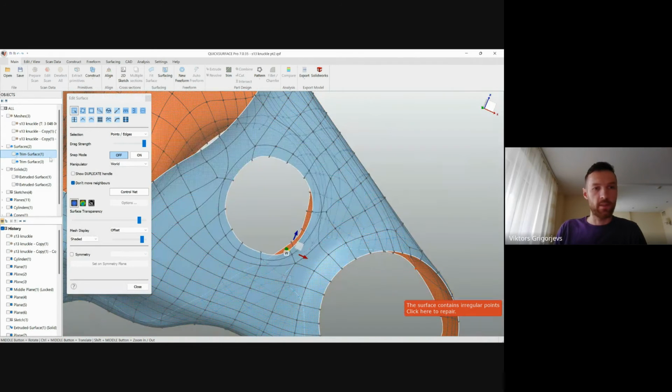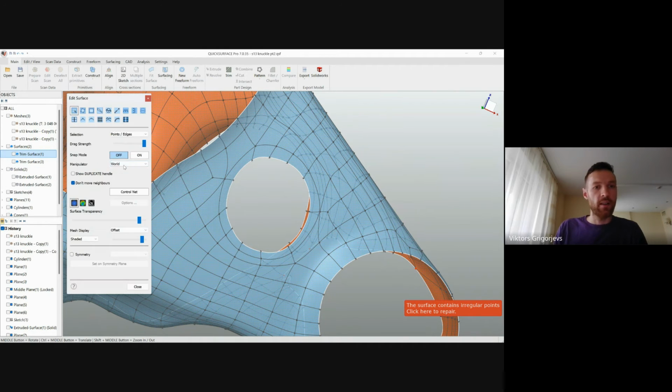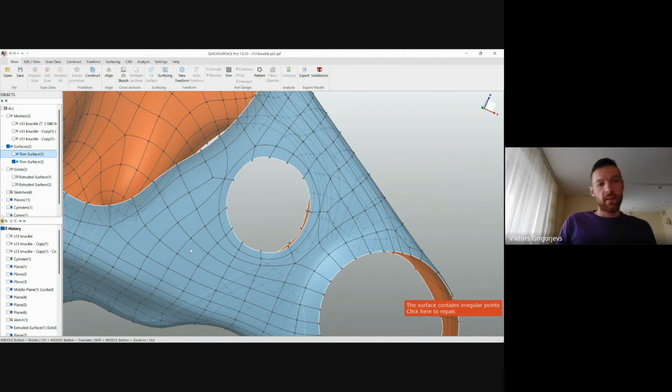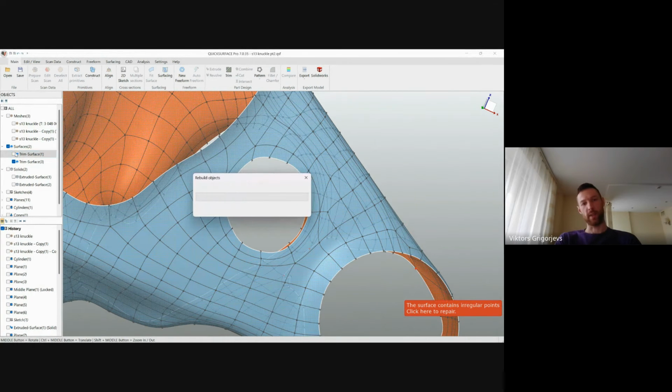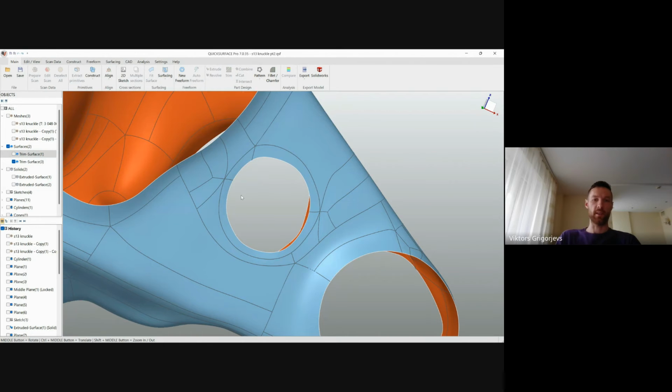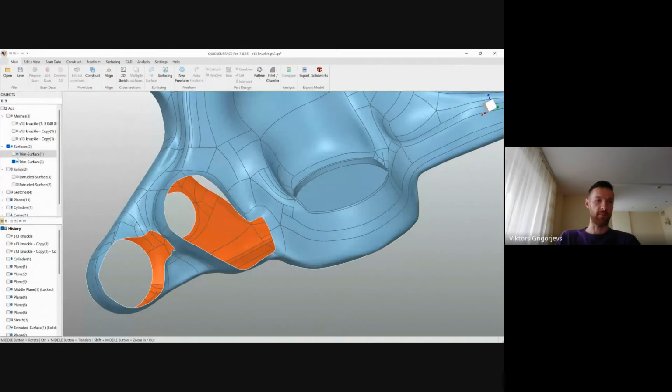So I have my overlap. Let's add some smoothness here. Keep close. Yeah, basically, what I told about extrapolating all these boundaries first, because every time I enter this edit mode again after going out, it has to recalculate all previous trims, so that takes more time.